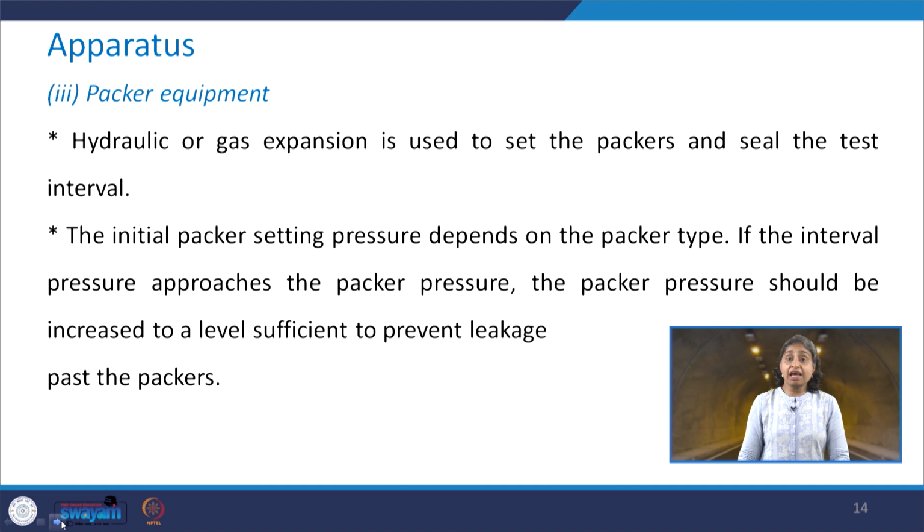Hydraulic or gas expansion is used to set the packers and seal the test interval. The initial packer setting pressure depends upon the type of the packer. If the interval pressure approaches the packer pressure, the packer pressure should be increased to a level sufficient to prevent leakage past the packers.